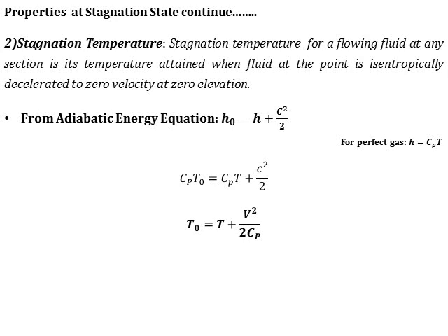the stagnation temperature. Now T0 represents the stagnation temperature, T represents the static temperature of the fluid at any particular point, and V square by 2 Cp also represents a temperature term. Remember, there should be dimensional homogeneity. So if all the terms are temperature, then V square by 2 Cp also represents temperature.